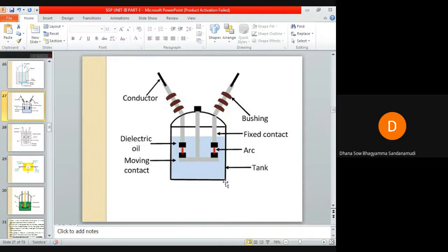From a practical point of view, the speed of the break should be as high as possible because a certain break distance has to be reached before interruption is likely to occur. The sufficient distance must be reached before the arc extinguishes between the contacts. The sooner it is achieved, the smaller the energy released in the breaker and the less mechanically strong the breaker has to be designed. So as soon as possible the moving contact should be moved far from the fixed contact, in order to avoid interruption of the arc before natural current zero.